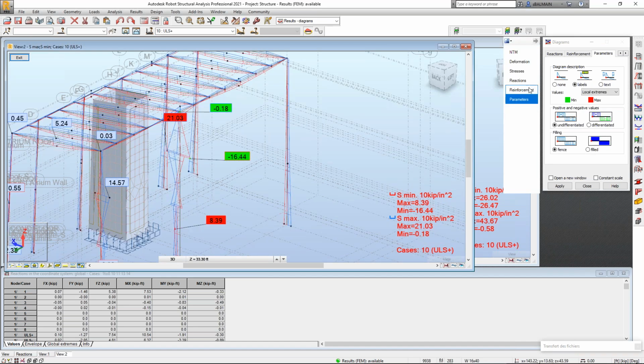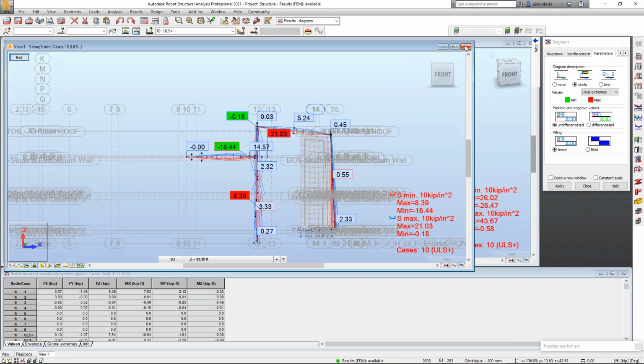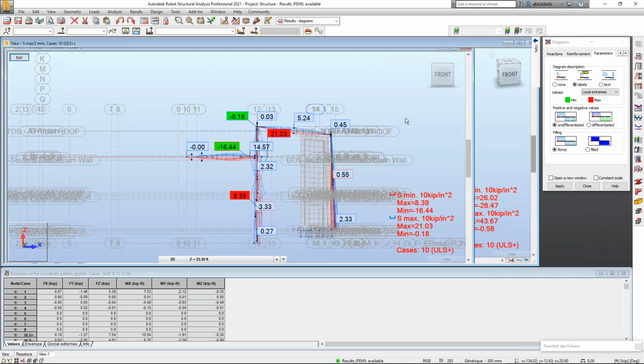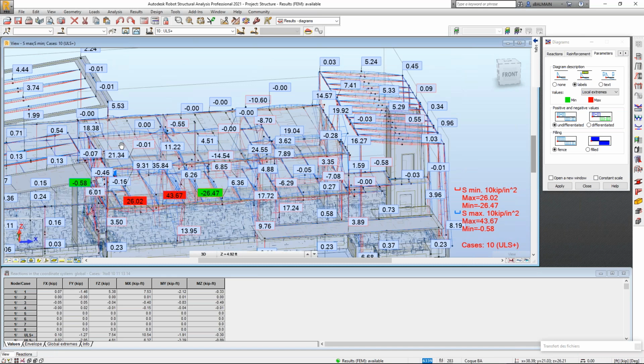Yeah, I will look if the global stress is fine according to the steel I have, and once globally it's fine, usually I will look, for example, here at the deflection in the middle. When it's fine, I will look at the same on concrete, but well, the global stress on concrete from moments or equivalent is not really an element to look at. So I look only at deflection usually on slabs. And here I would do the same with wood, I would say, if I have wood.